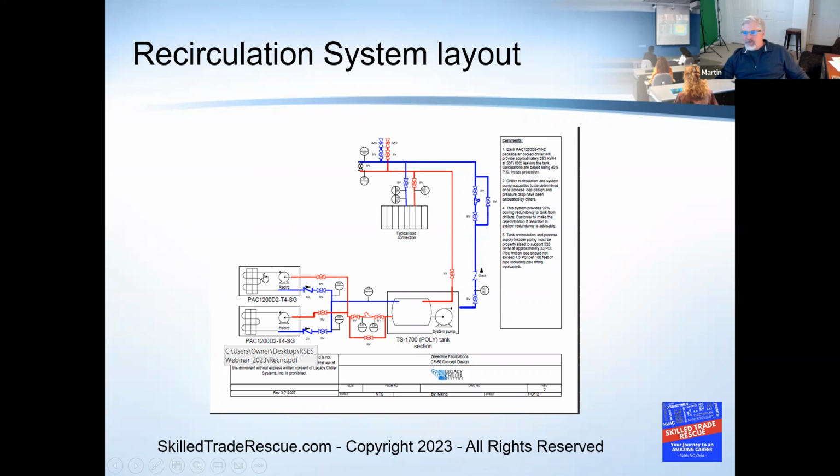So sometimes, especially on split systems, you can have oil return problems, you can have all kinds of issues because you're running that evaporator outside of its normal spec. So you want to keep stability as much as you can on these chillers. Okay.